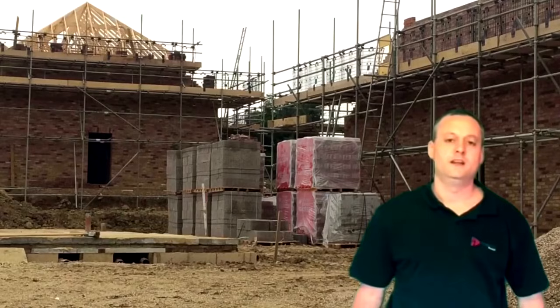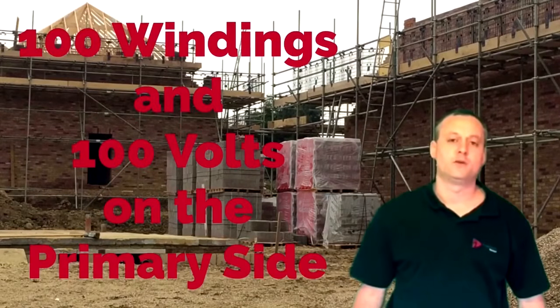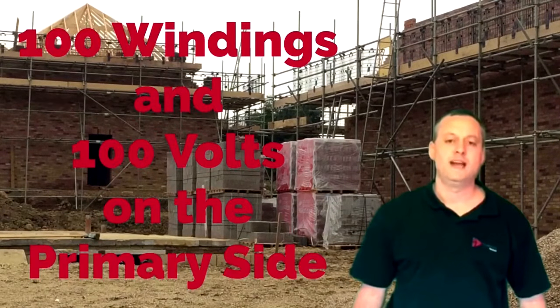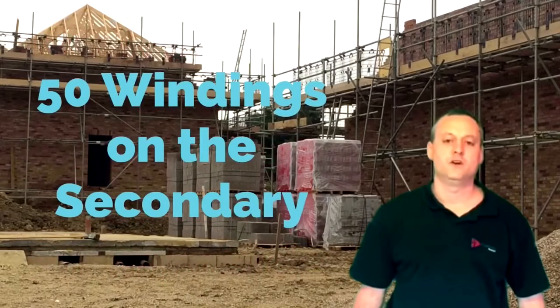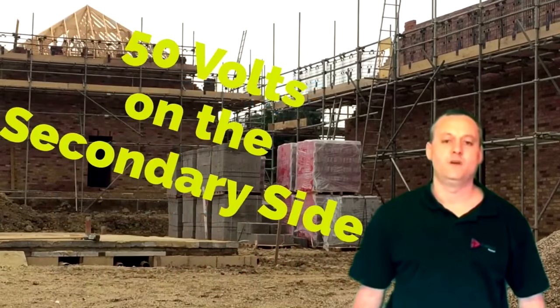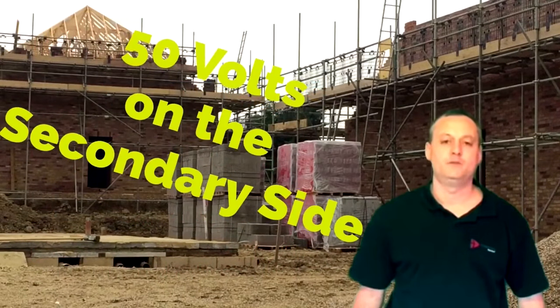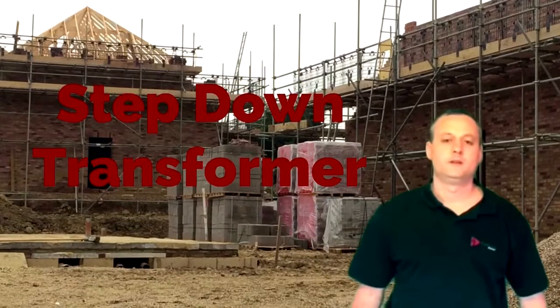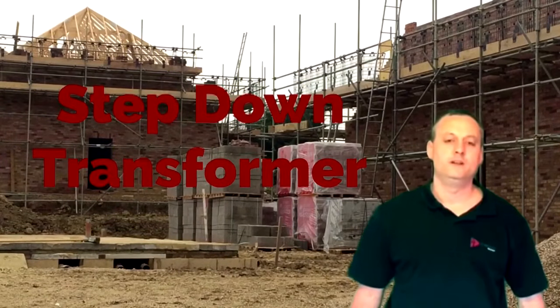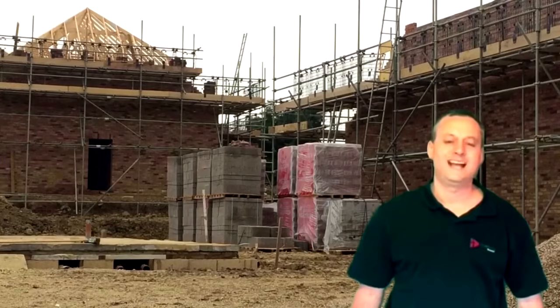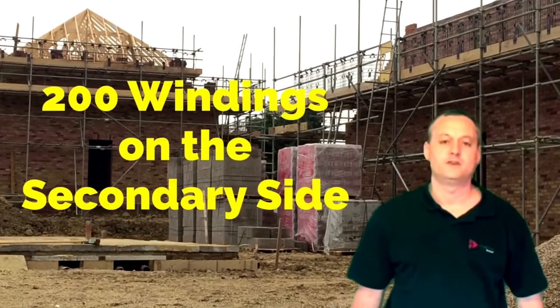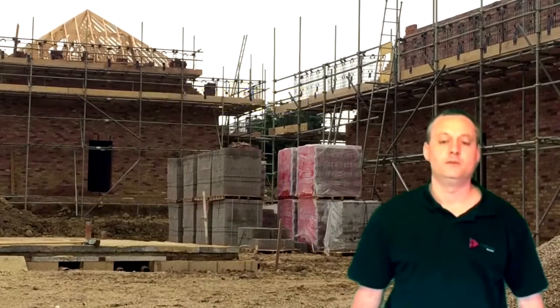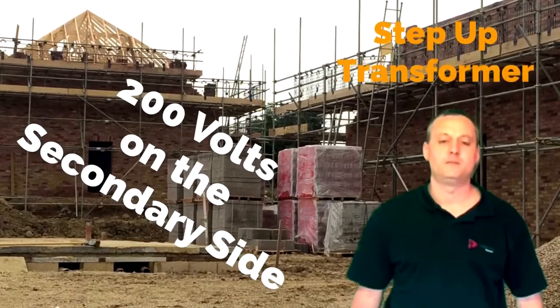We went on to see that if we had, say, 100 windings on the primary side and 100 volts, and we had only 50 windings on the secondary side, that we would have just 50 volts. Therefore, we would have stepped down the voltage onto the secondary side. Likewise, if we had 100 windings on the primary side and 100 volts and 200 windings on the secondary side, the secondary side voltage would be 200 volts and we would have stepped up the voltage.